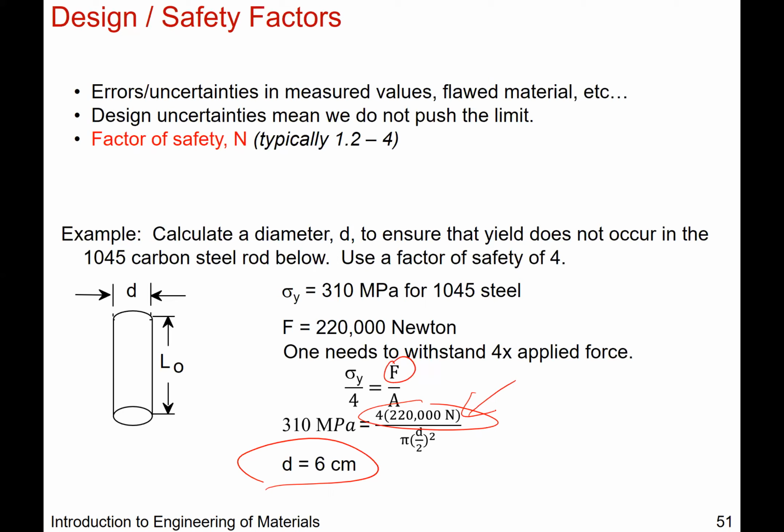If this cable is holding up people on a ski lift or something like that, obviously the design factor is going to be more. And of course you take other things into account, but this explains why you have a range for your design factors and how much you have to over-engineer for certain applications.